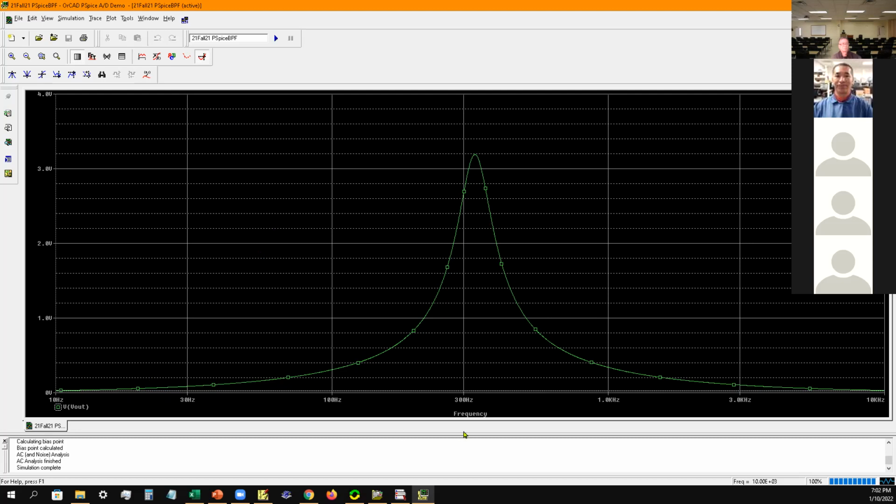But you see this line here. So you can use the arrow keys on your keyboard to move the cursor to the location where you need to look. The first one looks like it's at 30 Hertz. So you want to put it right over here at 30 Hertz. Now mine's sort of different, so let me see. That right there is showing that at close to 30 hertz, it's at 84.724 millivolt.